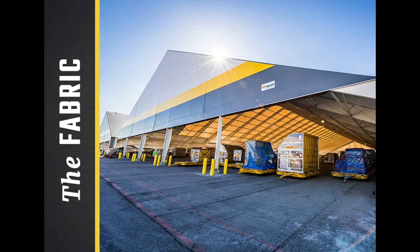First, we will focus on the defining characteristic of a fabric building, fabric itself. The biggest difference between fabric and steel buildings is in how the cladding material integrates with the frame. In a metal building, steel sheets are screwed to secondary members like purlins or girts, which in turn bolt to the rigid frames, creating an exoskeleton that actually aids the frames.